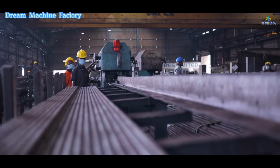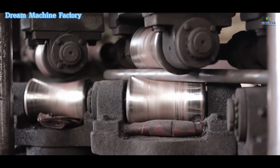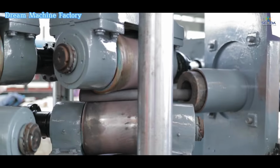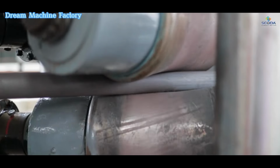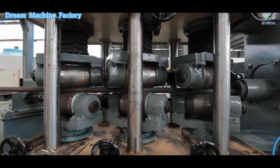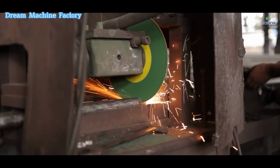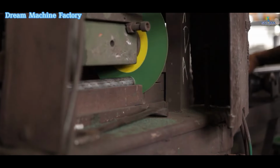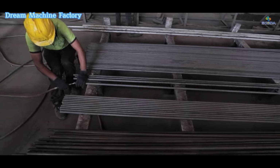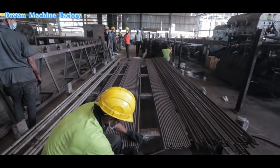Materials requiring straightening are often passed through a series of rollers, which apply controlled force at various points along the length of the material. This helps to eliminate bends and restores a straight form. The straightening process may be performed hot, while the metal is still heated, or cold, once the material has cooled down, depending on the type of metal and the degree of deformation.